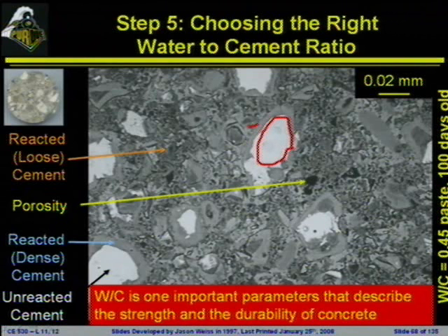We've got the dark gray areas, the dense CSH, and then we've got these mushy areas, which are really the pore structure, or the big pores that we're worried about. This entire thing makes up the pore system. But these really dark regions are the most porous of the regions. It's the ground mass portion of the overall microstructure.